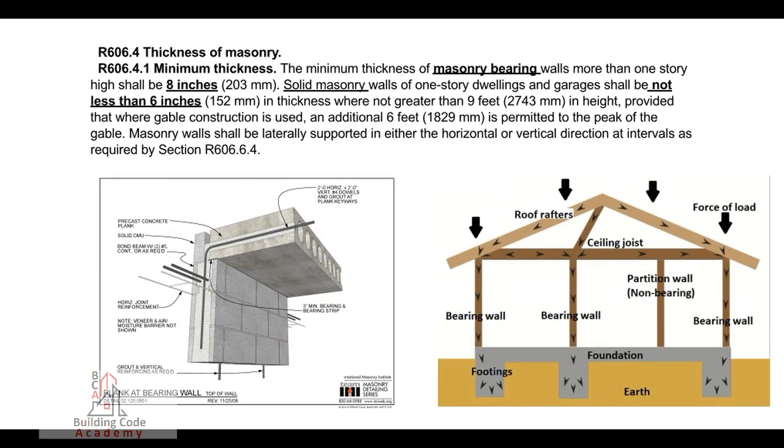Masonry walls shall be laterally supported in either the horizontal or vertical direction at intervals as required by section R606.6.4.